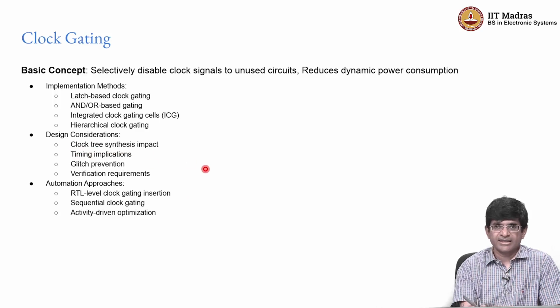Clock tree synthesis is something which we have not really touched upon much, because it has more relevance when you go down to the transistor level and start designing at the level of integrated circuits. But a clock tree happens to be a very important part of how the clock signal gets distributed across the entire circuit. In FPGAs, which is the primary target we have as far as this course is concerned, clock trees are already taken care of by the FPGA fabric itself, so we don't need to worry too much about them.